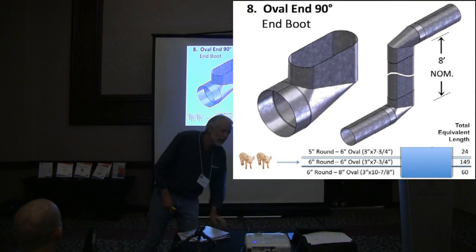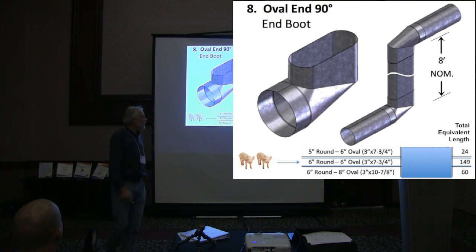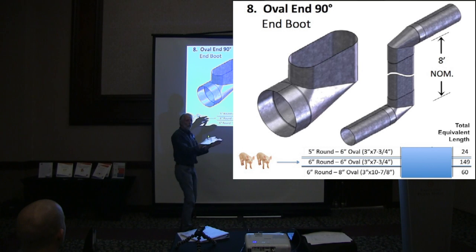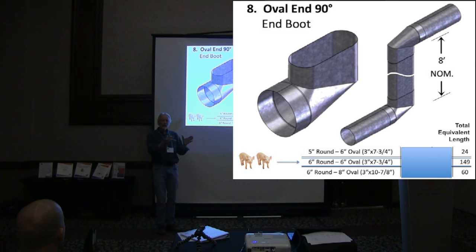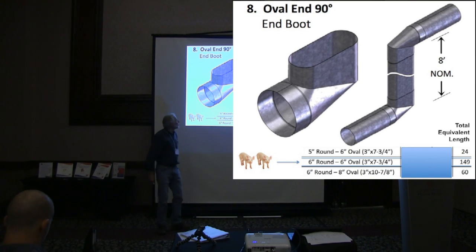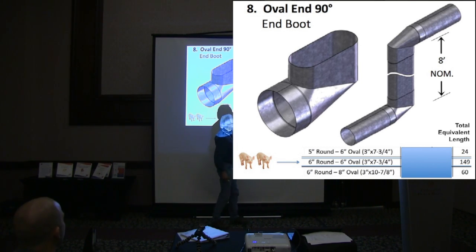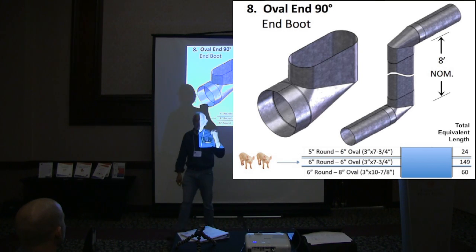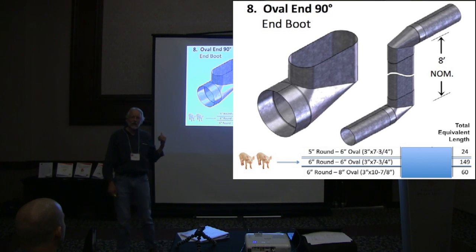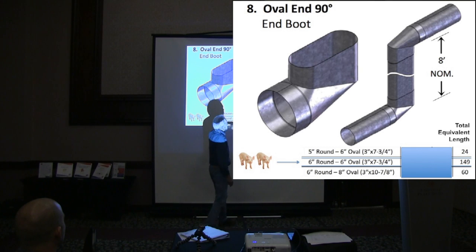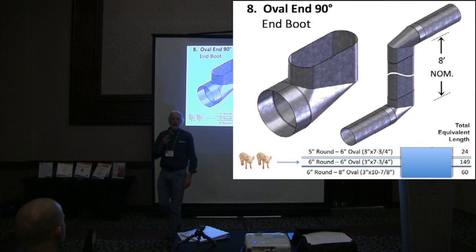We're getting into the whys of this. We spend a whole lot of time talking about moving air up a wall cavity. And oval duct, of course, is bad all by itself. A 6-inch oval stomped onto a 3.5-inch drops it down to 5-inch. But the real penalty is by going through 2 of these fittings, you now have 149 feet of equivalent length. This isn't mathematical gymnastics. This is actual measurement. 149 feet of equivalent length to get air from the basement ceiling to the joist system in Mrs. Smith's bedroom 1 floor up.